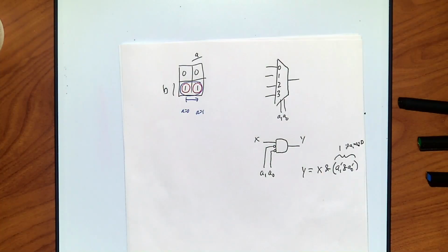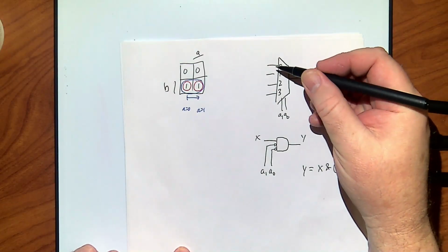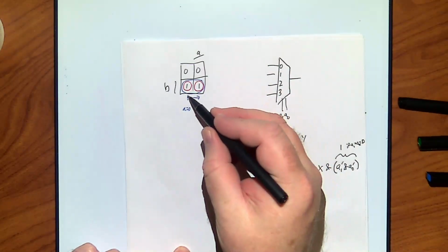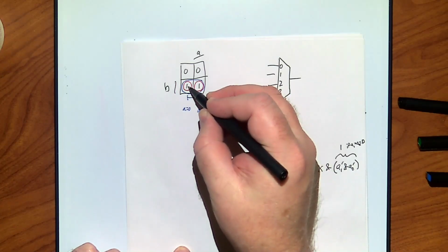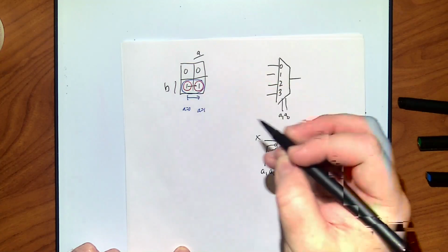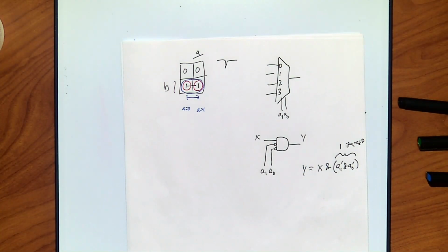It is a tiny encirclement. It's the encirclement of just that box. Which means if I'm switching on one of these, here in this position, when I'm going from here to here, since it's a tiny encirclement, it sees a 1 first and then a 0 and then a 1, so you get a glitch. Right? So the multiplexer is going to insert glitches all over the dang place.